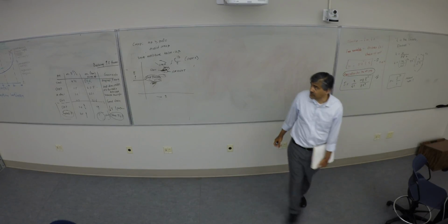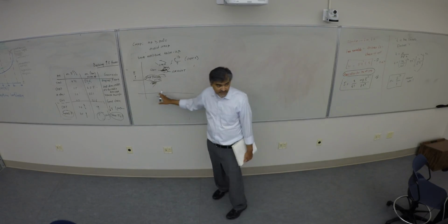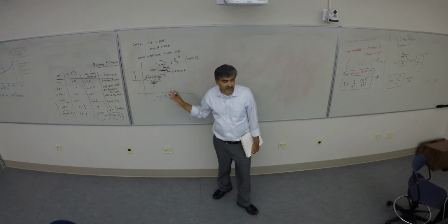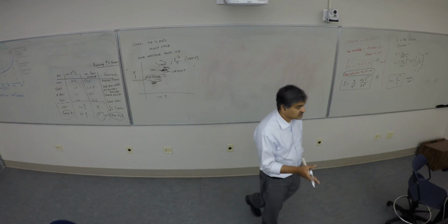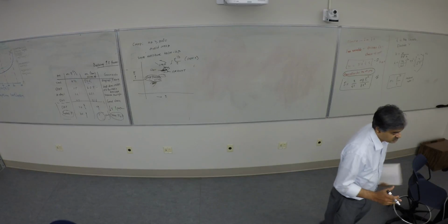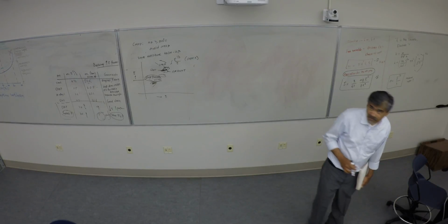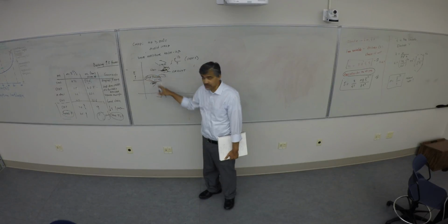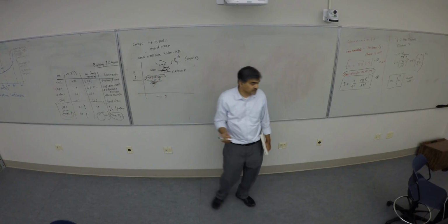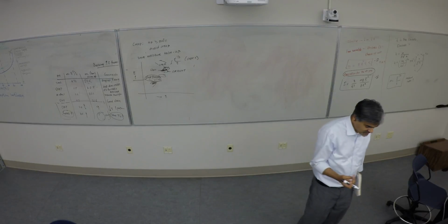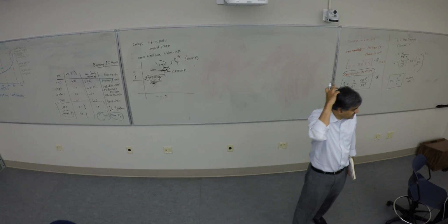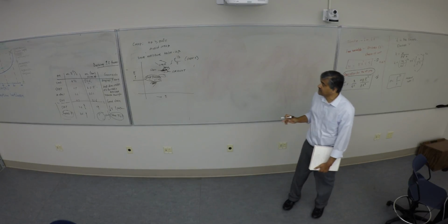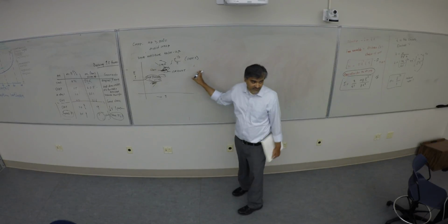I've just shown you one cross plot of modulus versus density, right? But the application would require you to look at other parameters as well. So you can selectively down select, right? And then once you have those, you can pick those down-selected materials and plot the other factors against them. We are just looking at one example for each case, but that may not give you all the answers from just one cross plot.